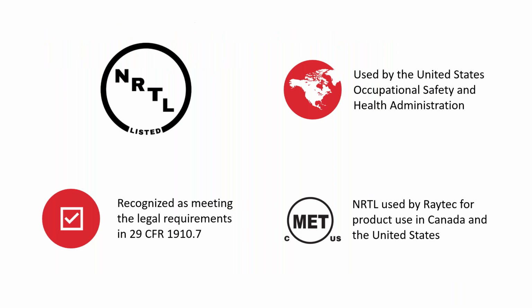Moving back to North America, so you have Class 1 or C1D1, Class 1 Division 1 and Class 1 Division 2. So unlike most countries, Canada and the United States do not base national compliance for hazardous area products on the IEC 60079 series of standards. Instead, a separate range of UL or CSA for Canada, standards exist which the equipment must comply with.